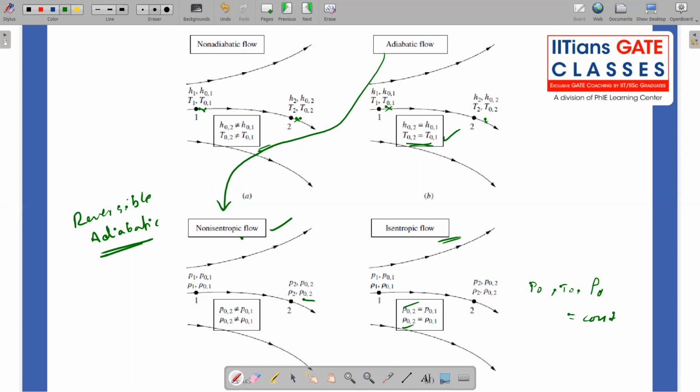In an adiabatic flow field, if the flow comes to rest, then we can define that particular quantity as a stagnation temperature, a stagnation enthalpy. To define a stagnation temperature, you have to impose one more condition, that is, a flow field of a calorically perfect gas. That is one more important term.